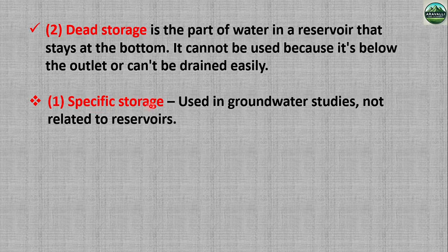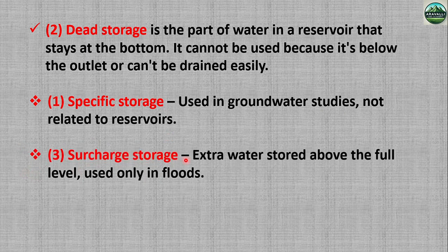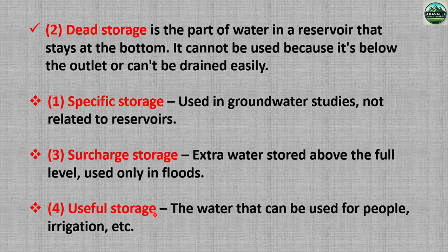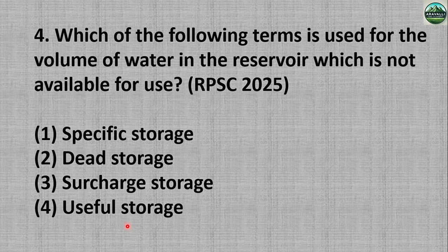Specific storage is used in groundwater study, not related to reservoirs. Surcharge means extra water stored above the full level, used only in floods. And useful storage means water that can be used for people and irrigation. Next, which of the following terms is used for the volume of water in the reservoir which is not available to use? The answer is dead storage.